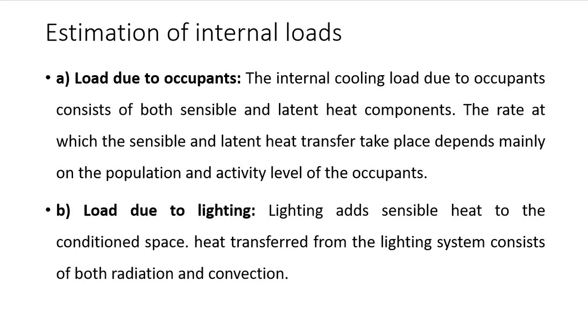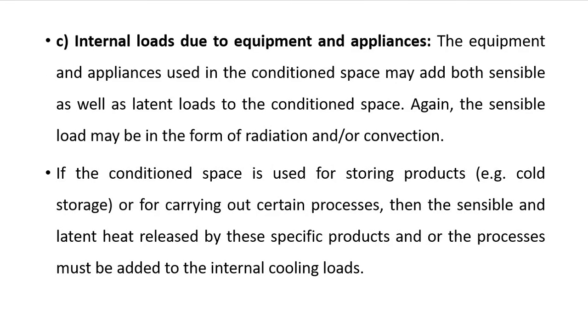Another one is load due to lighting. The lighting systems used for domestic as well as industrial purposes will cause sensible heat transfer to the conditioned space, both by radiation as well as convection. Also, the equipment and appliances, some motors used in the conditioned space may add both sensible as well as latent loads to the conditioned space.